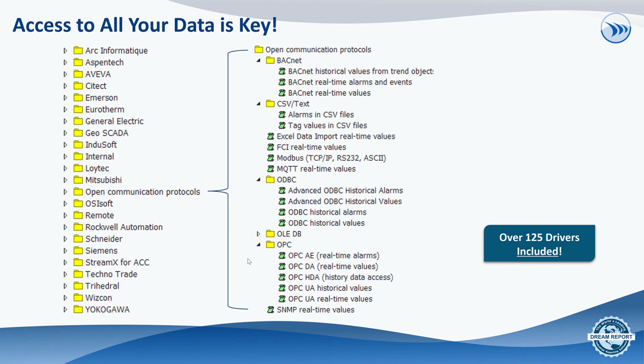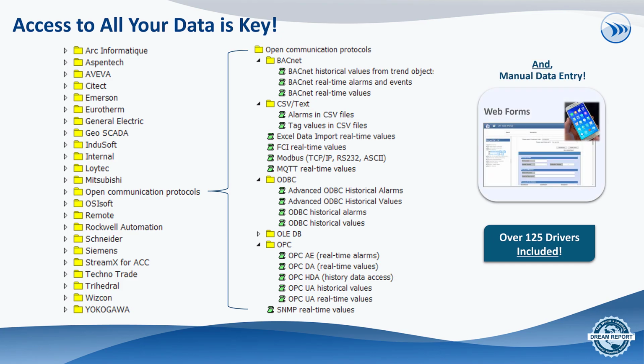If it's hardware, it's typically going to be a PLC or a data logger, a data recorder. If it's software systems, whether it's historical values, historians, HMI log files, real-time values from the HMIs, or alarm and event, historical alarm and event data. Additionally, we have a manual data entry driver, which allows you to manually enter data because ultimately the operator is the source of data for your reports.